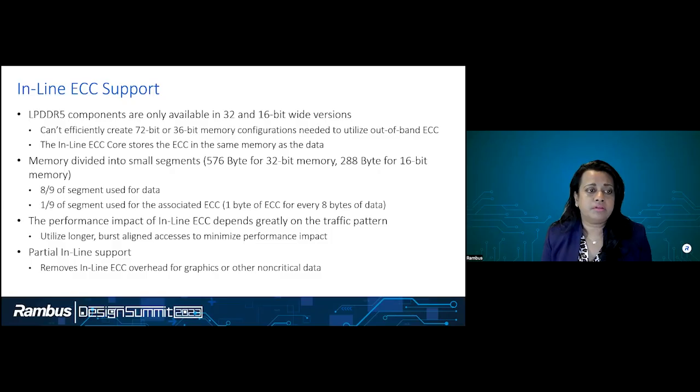And you would need an extra memory device for an out-of-band ECC. Now, with LPDDR5, the components are available in 32 and 16-bit versions. So you can't very efficiently create a 72 or a 36-bit memory to do out-of-band. So how the ECC is handled is by doing inline ECC, where the ECC itself is stored in the same memory as the data.